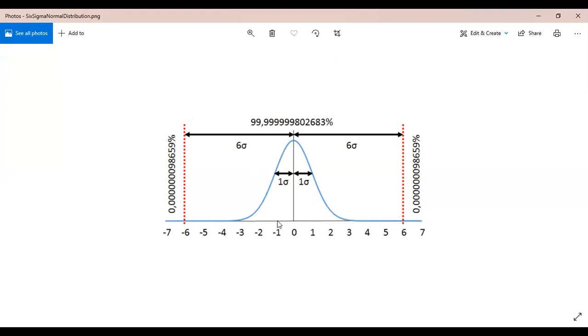I'm sorry, can you repeat that? For example, this is central tendency, right? Yes, the variation is between plus or minus 3. Yeah, plus or minus 3 if you plot the variation. So let's say it comes to this point, plus 3, and this side plus 3. So we have a total of 6 sigma, right? The assumption is if we have 6 sigma plotted from the central tendency, it would capture almost 99.7% of